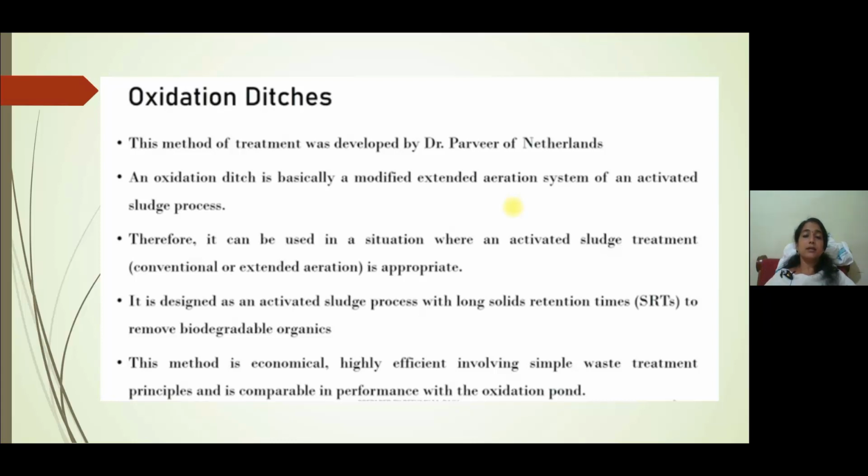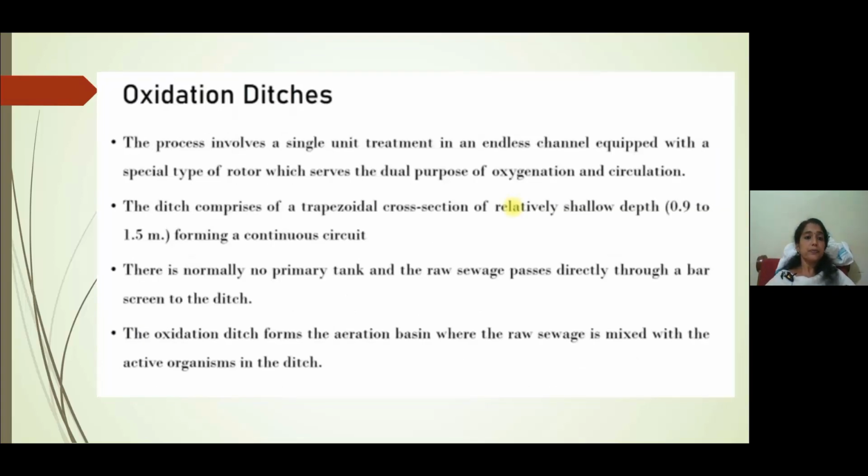It can be used in connection with the activated sludge treatment. It is designed as an activated sludge process with a long solid retention time to remove biodegradable organics. It is economical, highly efficient, involving simple waste treatment principles, and comparable in performance with the oxidation ponds.